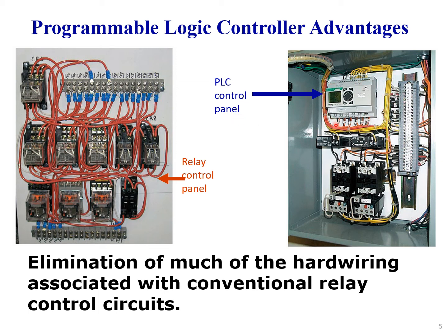So here you could see a PLC control. We have much less wiring. Elimination of much of the hard wiring associated with conventional relay control circuits is one of the main advantages of PLCs over relays.